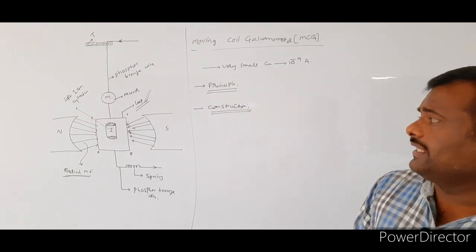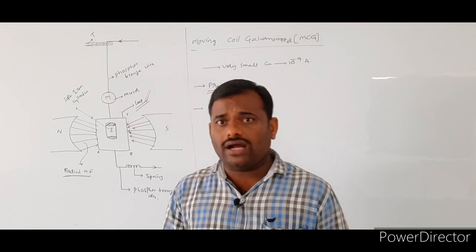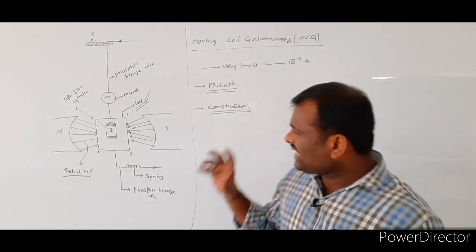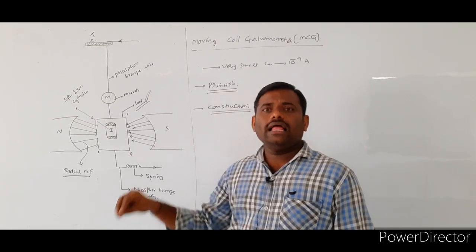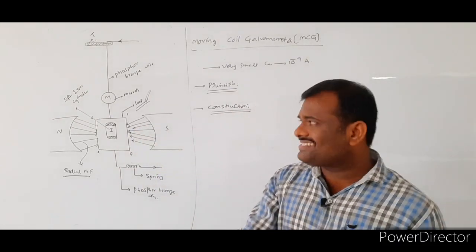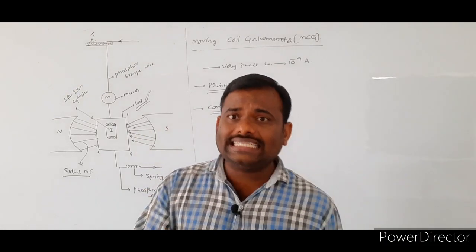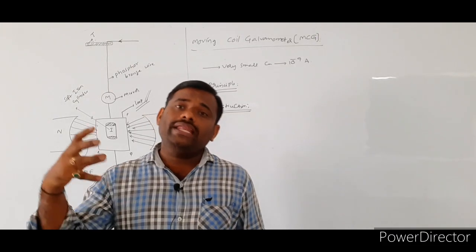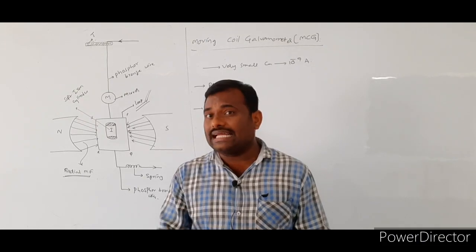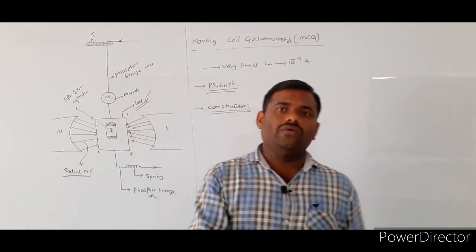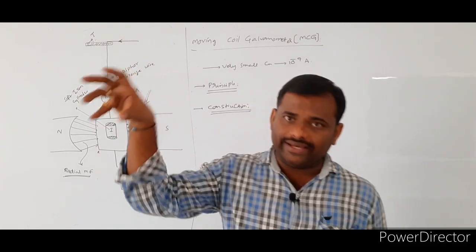I is indicating a soft iron cylinder. Again, what is the use of the soft iron cylinder? Whenever you place a magnetic material inside the loop, it will attract many lines of force through it. That means over the loop, maximum magnetic field influence will exist.